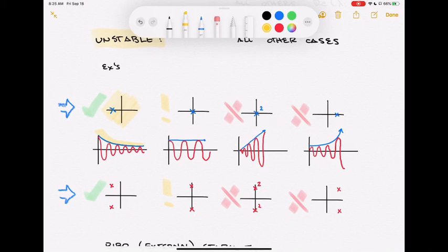If we look below, and we take two roots that are in a conjugate pairing, the real part of those roots is still negative. This might be the roots at -1 plus or minus j. The -1 part causes the overall modes to still have that e to the minus t decay, which is why the curve in red above, that oscillatory curve, still tracks that exponential curve, because they share the same real part of lambda being equal to -1, for example. The fact that I've got the roots off of the real axis indicates some oscillation going on there as well. So we get an oscillatory component that is exponentially decaying, that red curve. Again, this is still a stable condition, because you stuff energy into the system and it bleeds away. It doesn't cause any kind of exponential growth. If I move that root towards the omega axis, right?